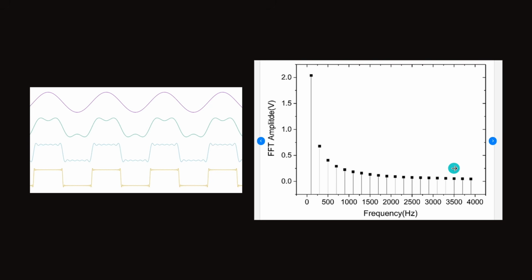And tweeter efficiency is only 1%, the rest is heat, and all those 4 watts plus 4 watts plus 4 watts plus 4 watts, 16 watts will produce significant heat, and your tweeter will be dead in a certain time if you really run your system at a clipping level. This is one of the reasons why more powerful amplifiers never burn your speakers.